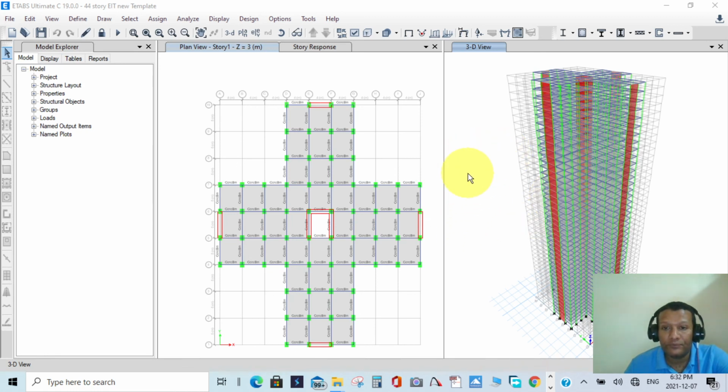And in this video, we saw what the response spectrum is, the mathematical formulation of the response spectrum, and the derivation of the equation, and the uncoupled equation of motion, and how we decouple it with q coordinates using mode shapes, multiply with the q coordinate and take the result into u coordinates.